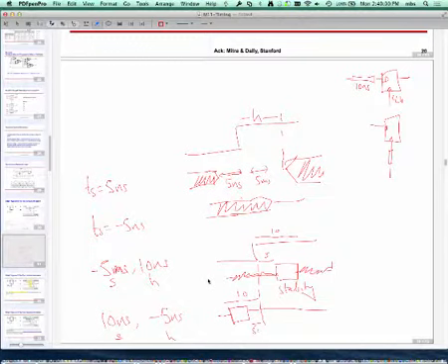There are also weird physical effects which happen. A chip which is running at 1 gigahertz as its top speed today, if you wait for 10 years, maybe the highest speed it can operate at is 800 megahertz. Of course, when Intel sells you a chip, they take into account that a PC's lifetime is typically not more than 5 years, so they just want to make sure that over that 5-year window, things will work correctly. After that, all bets are off. So they build in a lot of safety margin in their specifications.